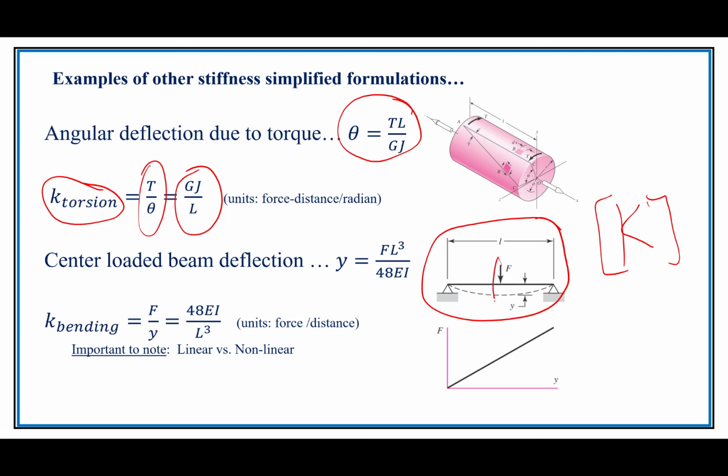Notably, the displacement and the force are in the same location. This isn't how it's actually done, but this is the main idea behind it, where you want to create elements that have stiffnesses by way of your element formulation. And the people who design FEA codes spend a lot of time and effort on their formulation of elements. They also mention the shape of the element has a big deal to do with these stiffnesses.